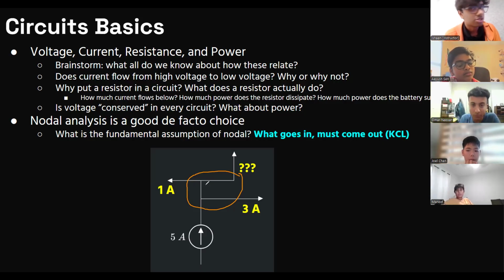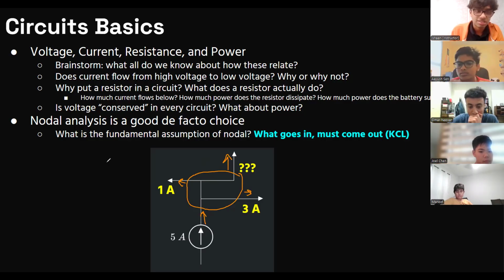So probably the most important part of nodal analysis is either redrawing your circuit to be pretty and not have to worry about these wacky nodes, or recognizing what the wacky nodes are and drawing boxes like these and just drawing arrows going into the box and out of the box, and saying what goes into the box has to equal what comes out of the box. That's the reason I draw a circuit so strangely like this.